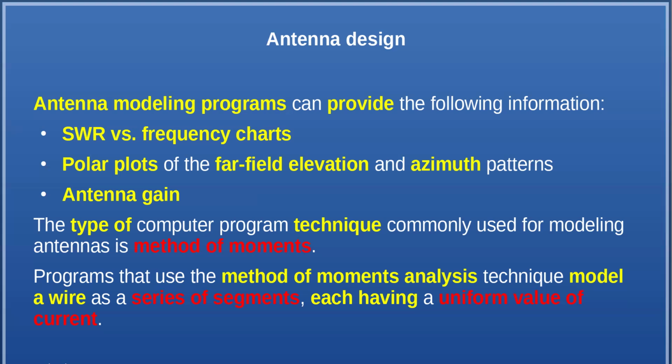But you have to have a minimum of 10 segments per wavelength. Otherwise, you don't get very good results. It's kind of like, we mentioned the Nyquist sampling where you've got to do it twice for the frequency. Well, same kind of effect here. You've got to have at least 10 samples per wavelength distance.